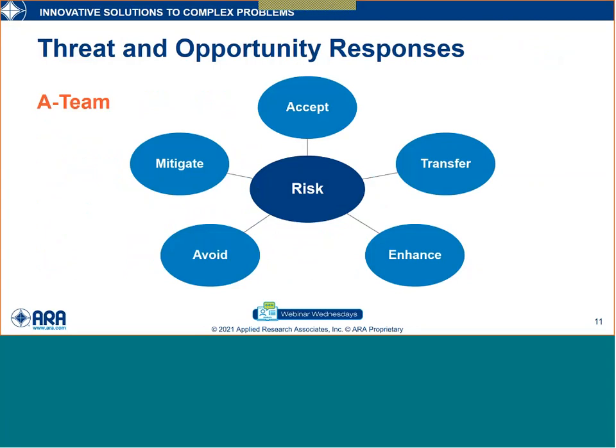And those other things, a way of treating threats and opportunities that we identify in a risk management assessment, are often referred to as the A-TEAM acronym. And you see risk at the centerfold here. And we just spoke about mitigation. However, we can just accept the risk and incorporate that into the additional effects of those risks occurring. We could transfer the risk. One means of doing that is through perhaps a design-build contract, where we perhaps sometimes excessively try to transfer risk